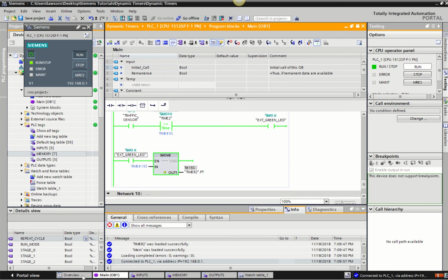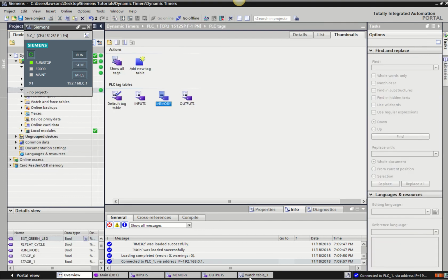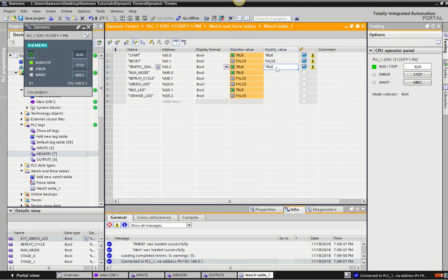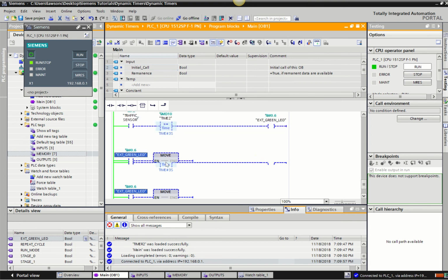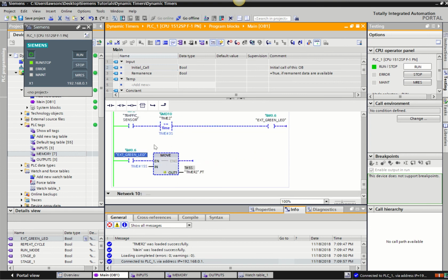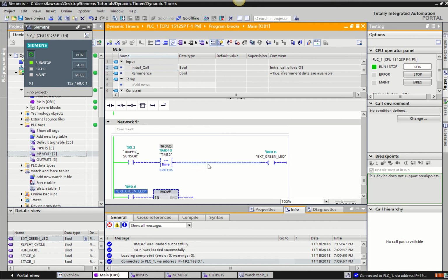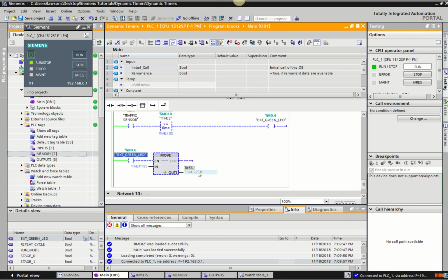So now if I turn the traffic off, so say the traffic has gone away, back in here, put this to false, modify that. Now when this comes back around to green, back into main, you'll see it times up. When it gets to 3 seconds, it didn't have heavy traffic, so it's not going to extend the green. So it's not going to change now to 15 seconds. See that when it gets to 3 seconds, this part was high, but it hasn't got this part. So extend green now goes out. So 5 seconds never changes to 15 seconds.